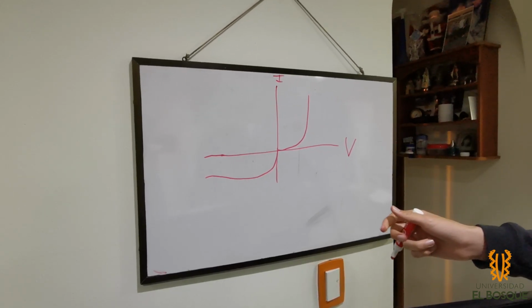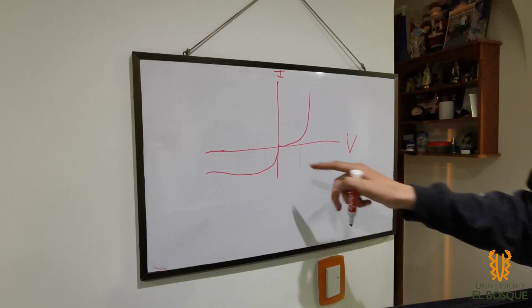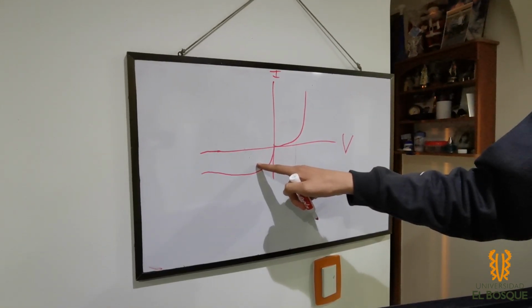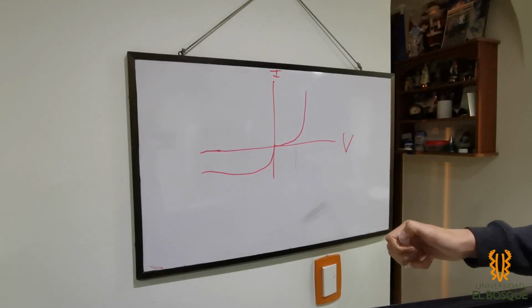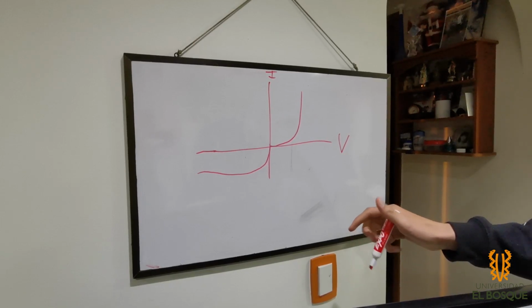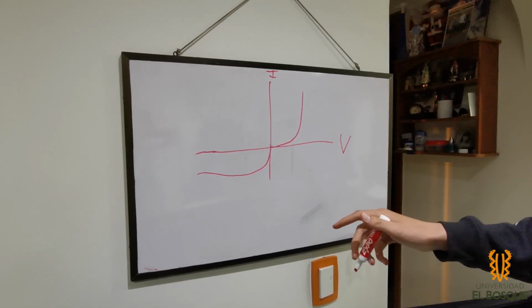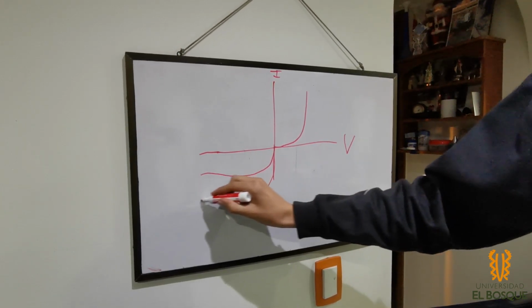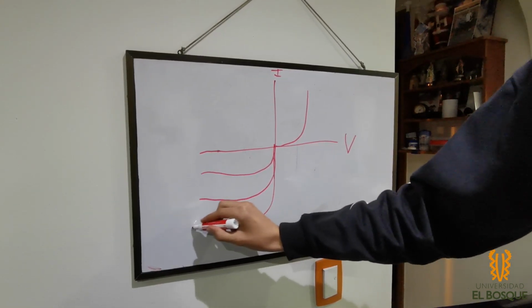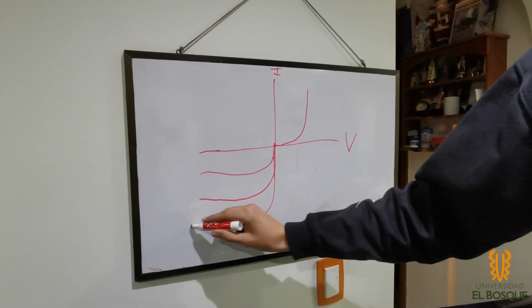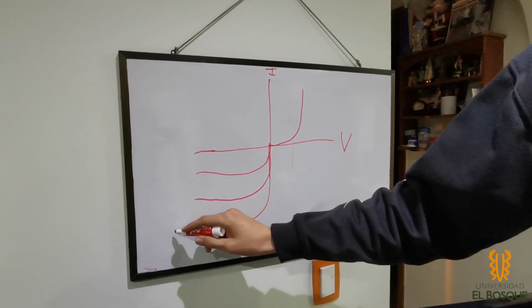It depends just a little bit on the voltage: as the voltage gets more negative, the depletion region gets larger, and it is easier to get free electrons and holes. But at a certain point, the depletion region is not going to get much larger. So this magnitude depends only on the light. The more light, the higher the current.